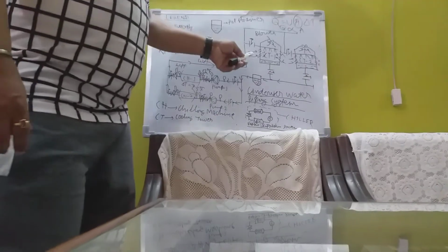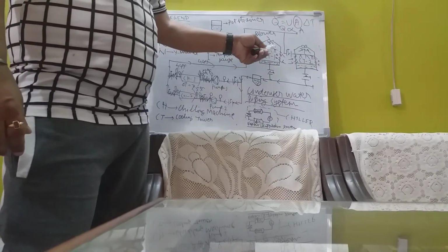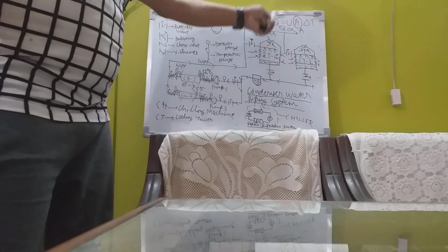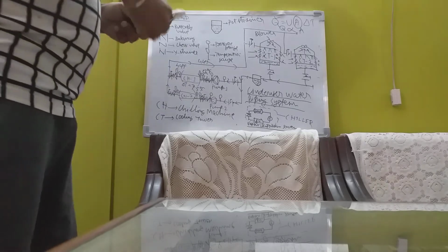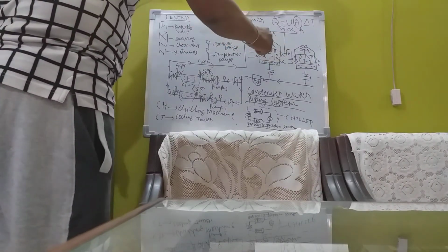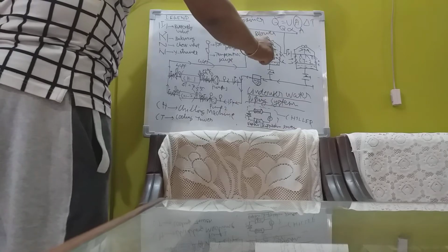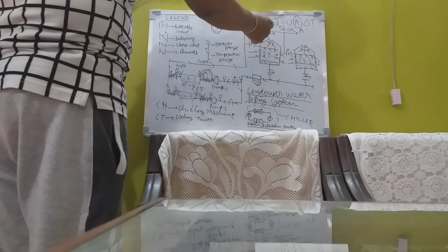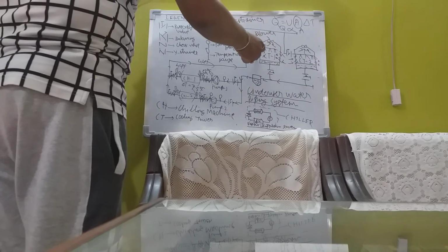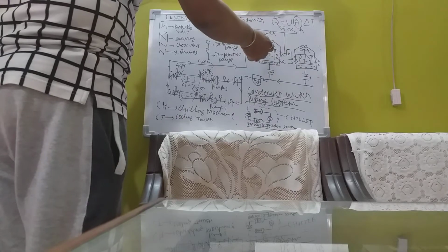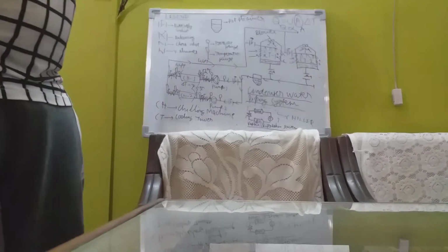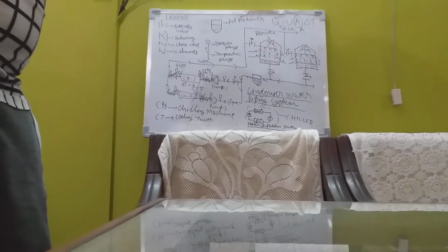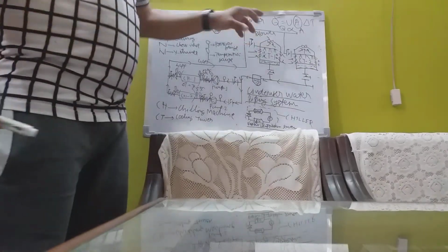So what happens? This cold air which is coming inside picks up heat from the water, itself gets heated, and passes through the blower to the outside. This is the cooling tower structure. In the cooling tower structure, these are outside fields in which there are small apertures, meaning holes. This blower is sucking air from here. This air goes through this part and passes through this sprinkled water. So, very small particles of water get exposed to cold air. There is meshing up, there is mixing, and as a result, there is cooling.